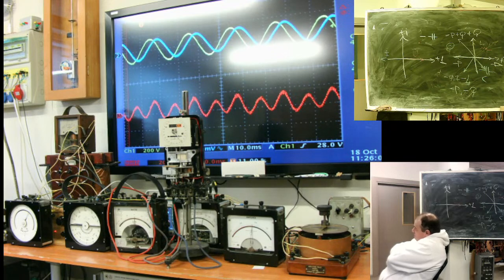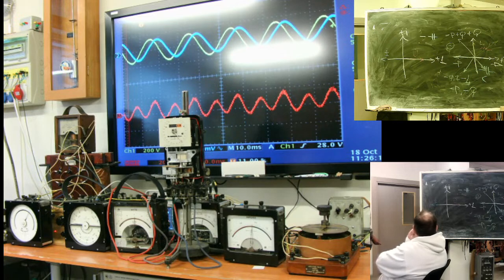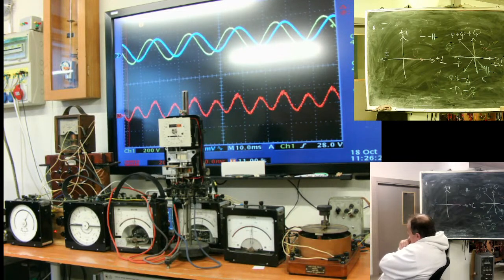When will we get positive active and positive reactive? What do we need? If we would like to get both positive, when the current is lagging. Yeah, we would like to see lagging current. Yes.